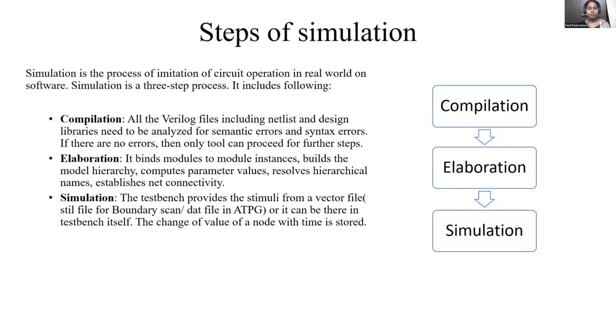In elaboration for our test tool, we are building a flat design, considering its hierarchy and everything, and seeing if there is some unresolved module within the module. There is a possibility that we misconnected a certain input to a certain output and it's dangling somewhere in the design. So elaboration checks for all these unresolved modules also.